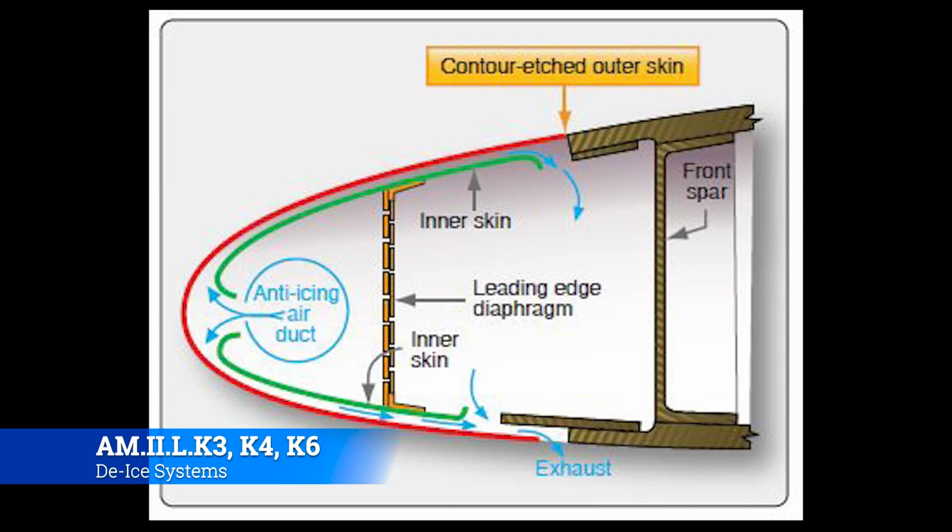Okay, so here's the inside look of what a heated leading edge potentially could look like. Notice you have the front spar in the back, and then the leading edge, whenever you go to install it, is more or less just a bent piece of sheet metal that gets riveted right there on it. So inside you have this blank space.